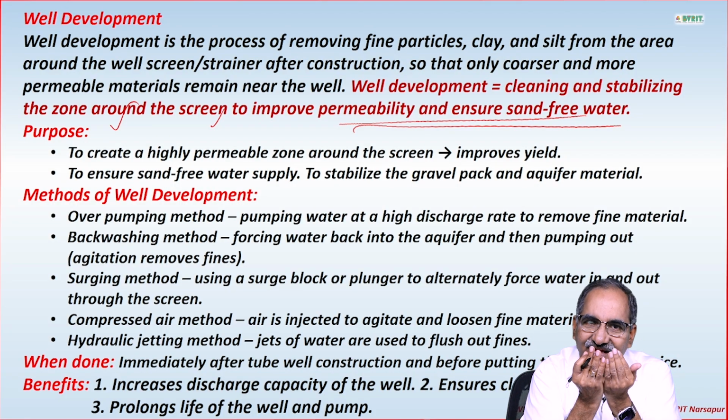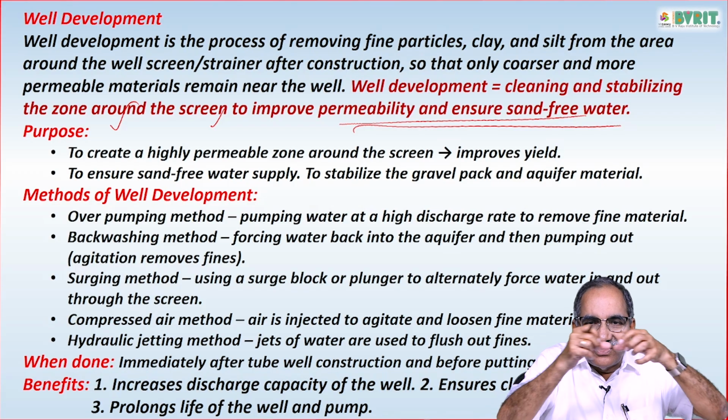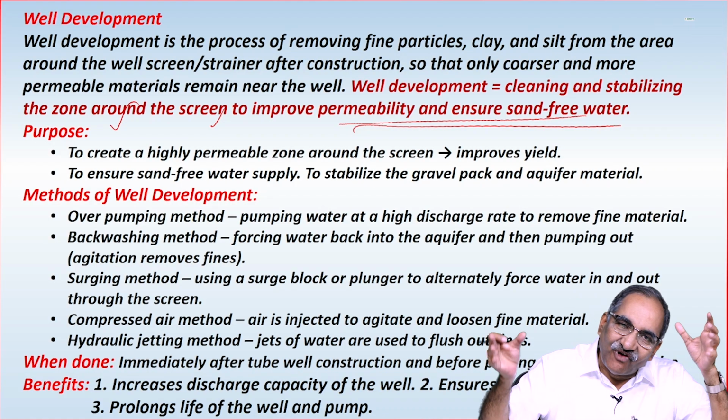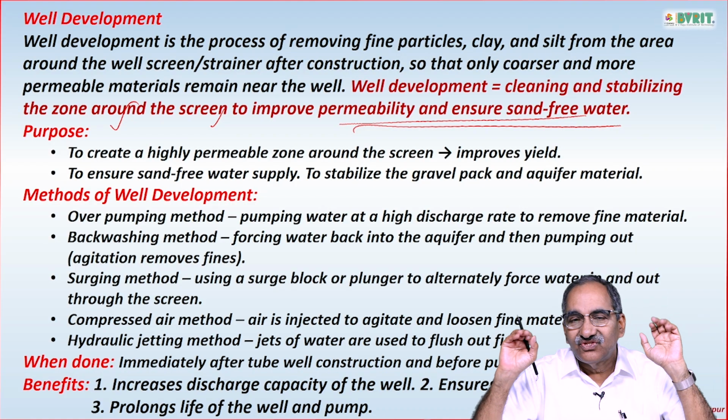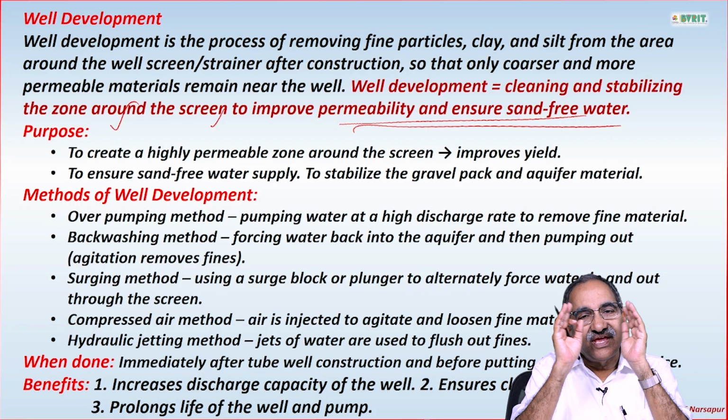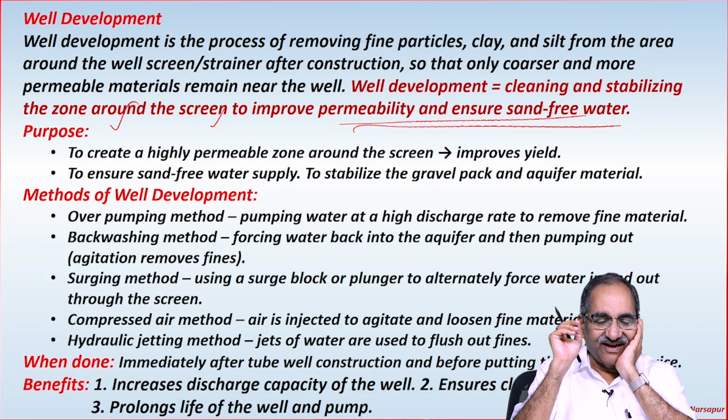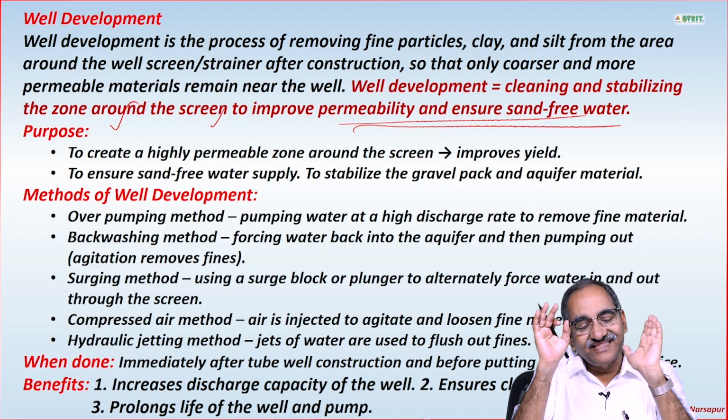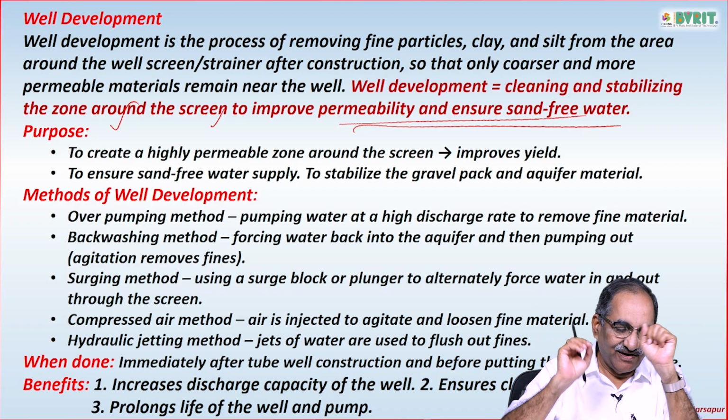Once the well is constructed, you need to remove the fine particles so that only the coarse particles are surrounding the strainer, and this method is called well development.